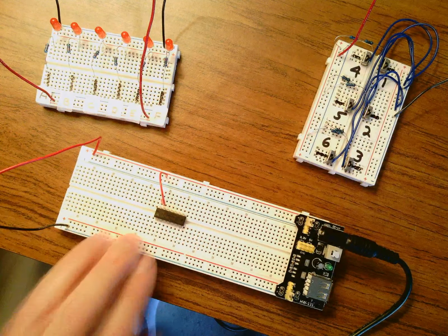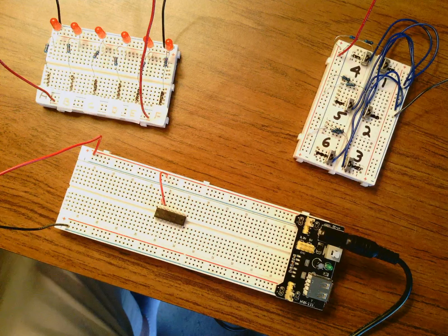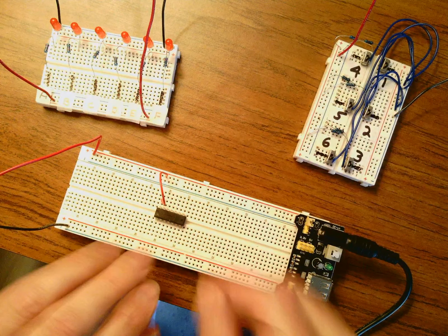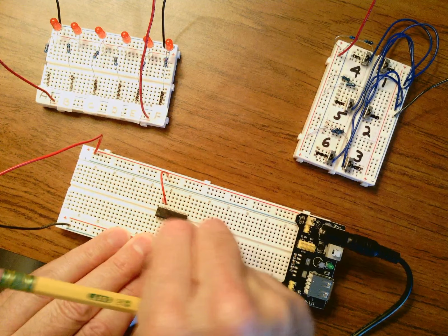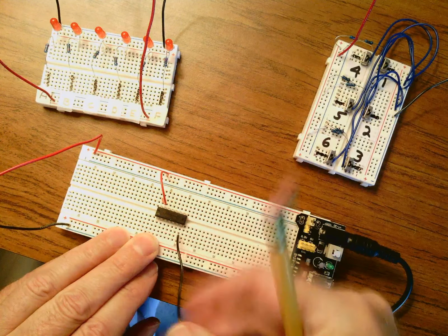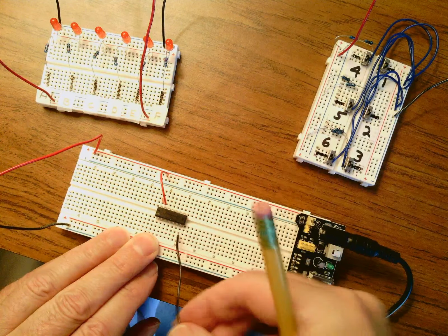And then you're going to get a small black or blue wire. I don't care if you get black or blue, and I want you to get the ground pin, which is pin 7 in this chip, like that, and I want you to connect it to the 0 volt rail or the ground rail directly below like that.